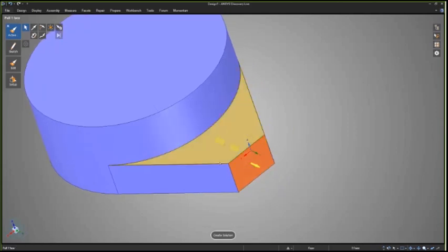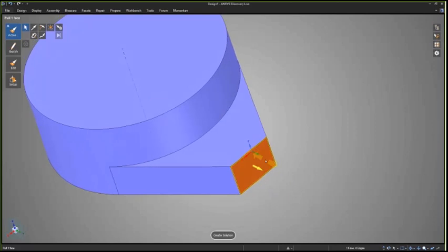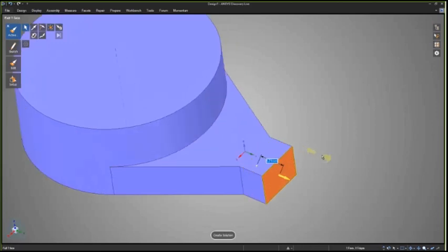So the primary way to change the behavior is to change your selection. Direct modeling is very hands-on, so why look through options? Interact with the model instead. By selecting this face, holding Control, and double-clicking this edge, it grabs that entire loop, and I let go of Control and drag, and now you'll notice that by selecting the edges, it's ignoring the faces.